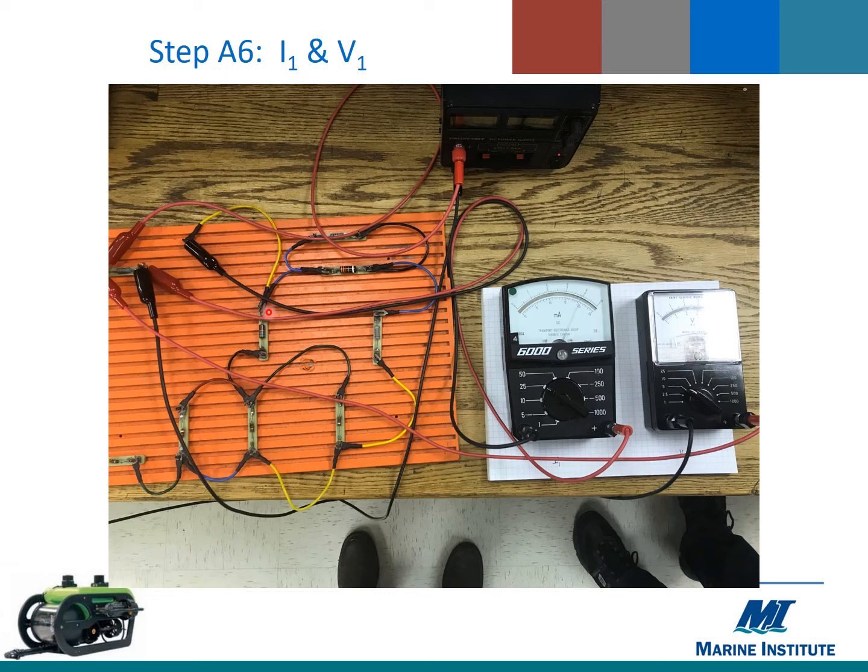Now the voltmeter, however, we have moved, and you'll notice that our voltmeter here, its positive terminal now is connected through this lead to the left side of R1, and that is because the left side of R1 is closest to the positive terminal of the power supply, so that is positive for its voltage drop and positive for the connection of the meter. Now the negative terminal of our voltmeter has been connected, and you see it goes under the table here, but it comes back up and goes on to the right side of R1, which would be the negative side of R1 if we marked its polarity on figure 6.1. And so the voltmeter is across R1, it will measure the voltage for resistor 1.